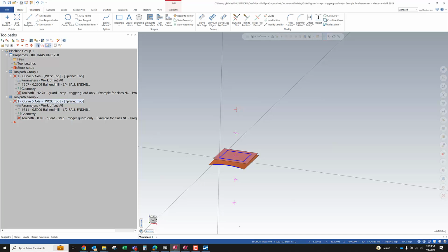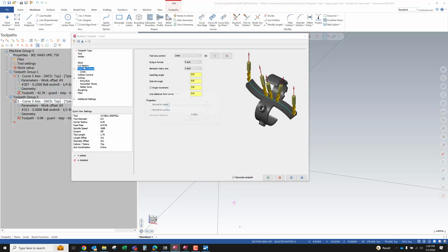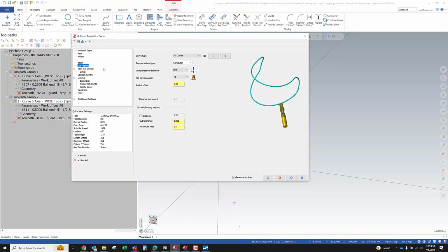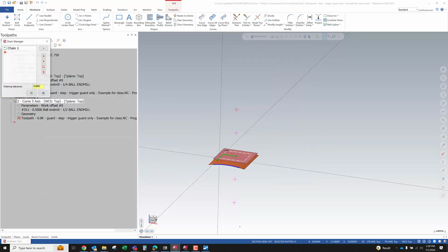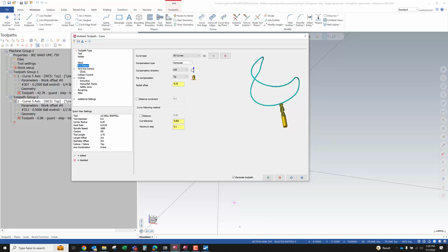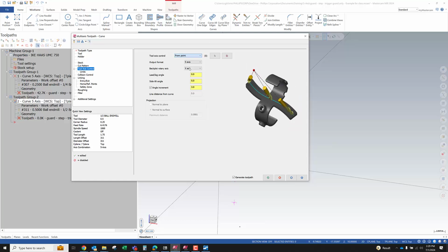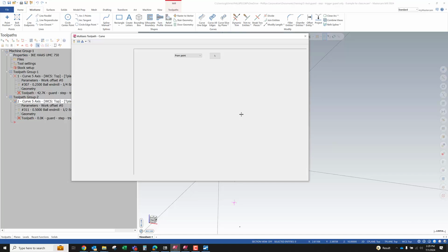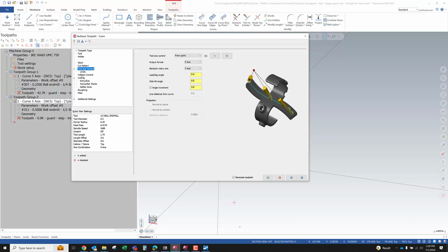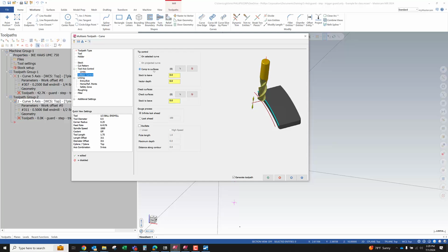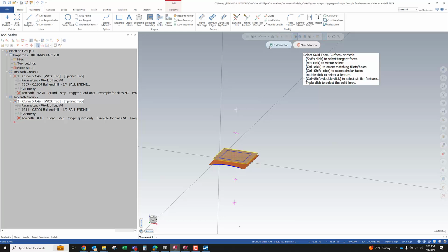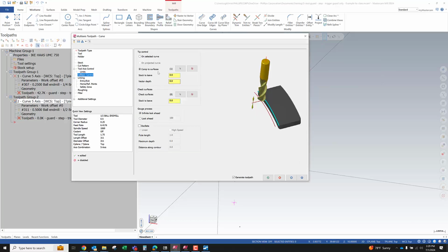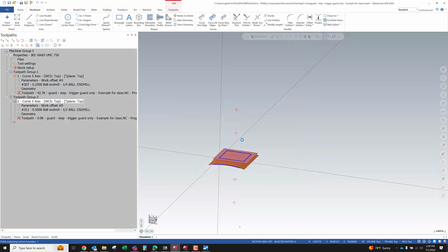So curve 5-axis, I'm going to go into the parameters. We've got our cut pattern selected. Yep, cut pattern's in. Okay, the chain's in. Tool axis control from a point. I'm going to select that upper 10-inch point. Collision control, we're going to do comp to surface, up to this flat surface here. And everything else default.